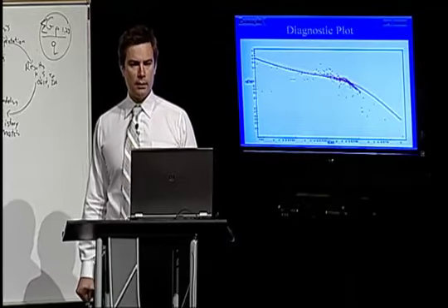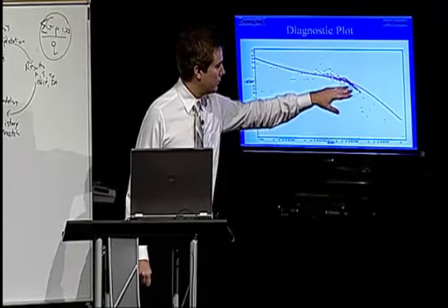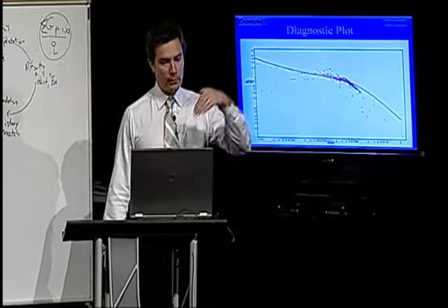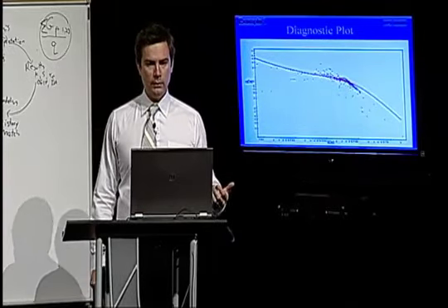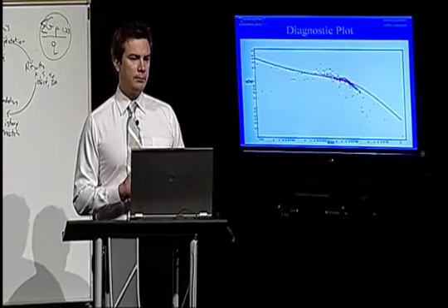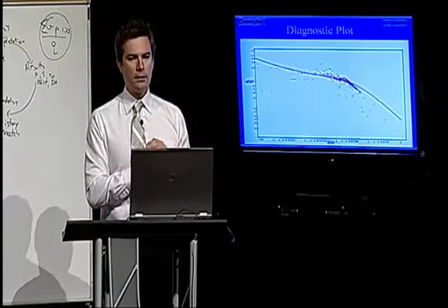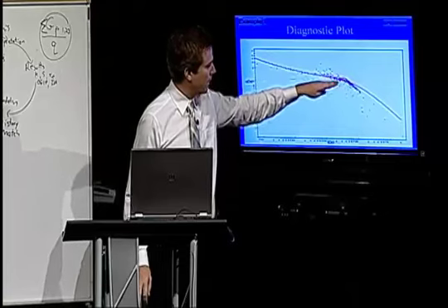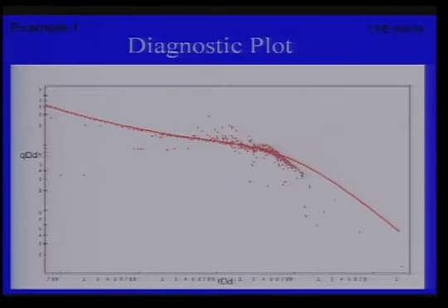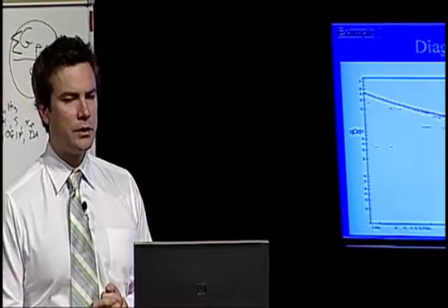And that would be a mistake, because that drop off in the data is due entirely to liquid loading. So it's the reduction in productivity because of that increasing column of liquid inside the wellbore that's causing this behavior. It has nothing to do with seeing the boundaries in the reservoir. They're two totally different things, but they look similar on these plots. So that's why I bring it up as an important diagnostic. Now, there's a couple of things you can do about this.